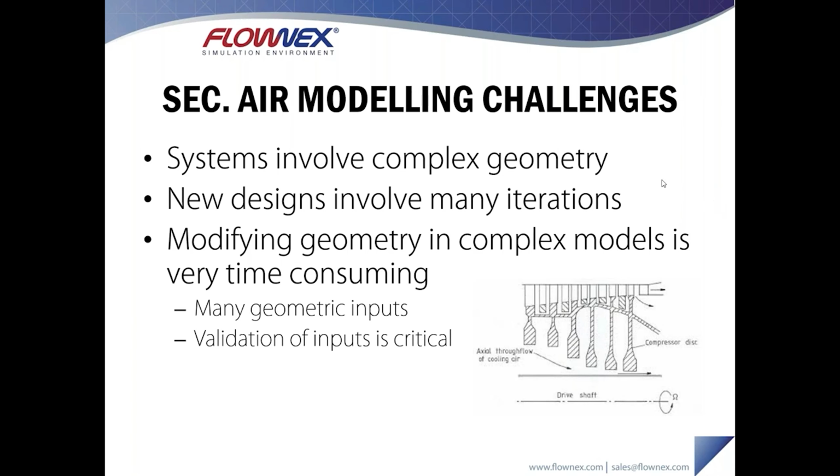The geometry here is very complex, and to correctly model this flow, it's important to put in the profiles of these walls to calculate windage, as well as the radial locations to ensure that any radius changes in the flows are correctly accounted for, along with all of the other traditional values you would expect, like lengths or diameters.